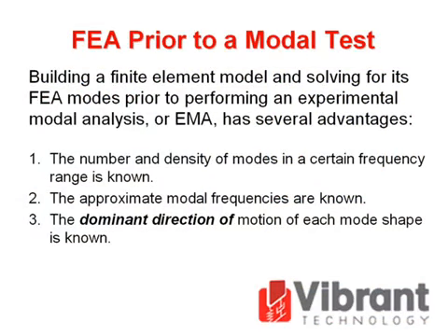Building a finite element model and solving for its FEA modes prior to performing an experimental modal analysis, or EMA, has several advantages. 1. The number and density of modes in a certain frequency range is known. 2. The approximate modal frequencies are known. And 3. The dominant direction of motion of each mode shape is known.